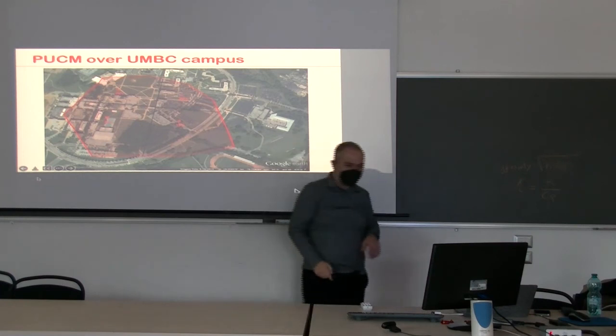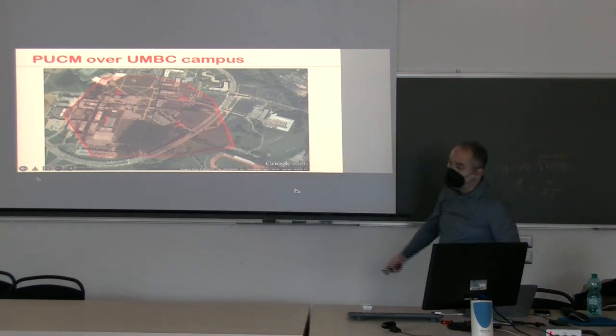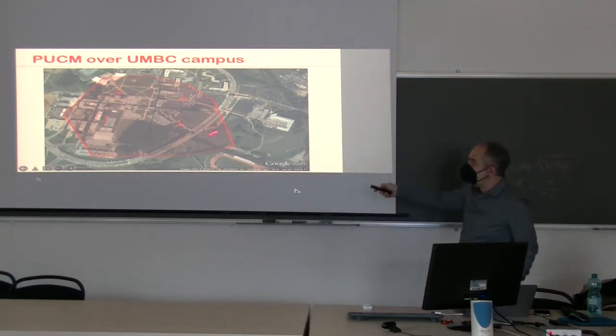So we divided this area into 4 sectors, and we set up the UCM for each of these sectors differently. So this was mainly grass, basically. I mean, almost no buildings. This we take the average building width and building height. This we set up mainly as asphalt, and this is the mixture.